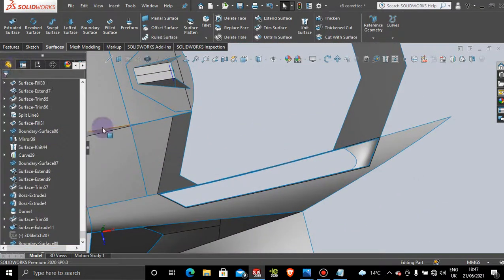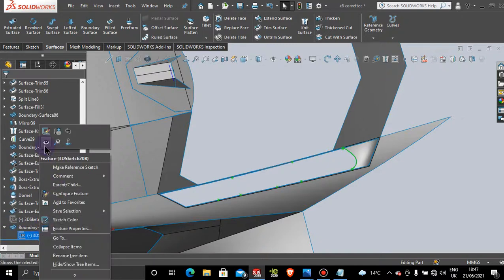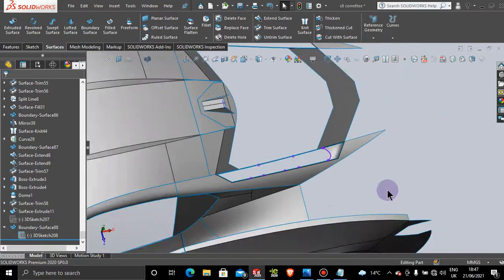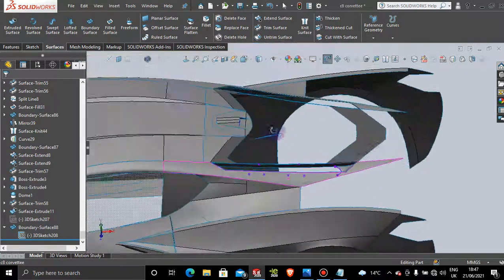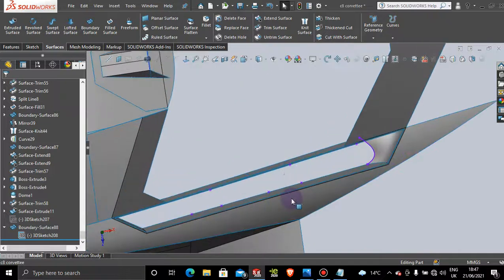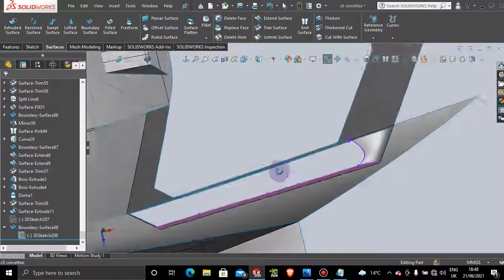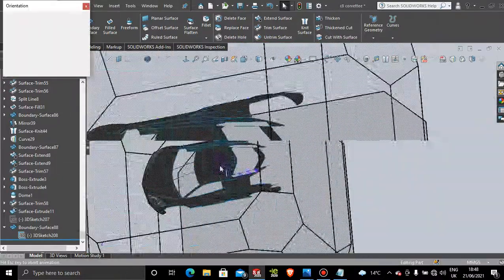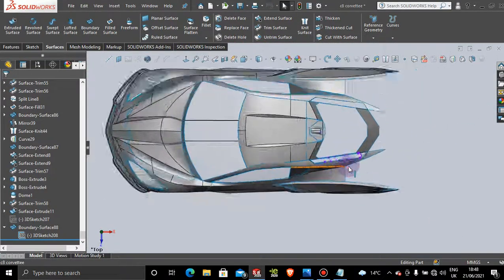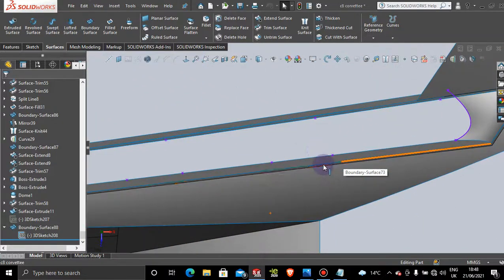And then let's go into the feature tray and then bring back that 3D sketch, because we need those points. So show those points. Okay, so there are these ones on the bottom here, these ones on the top. Let's get to the top of this thing again. And we want some lines running across, and some lines running inside that area.